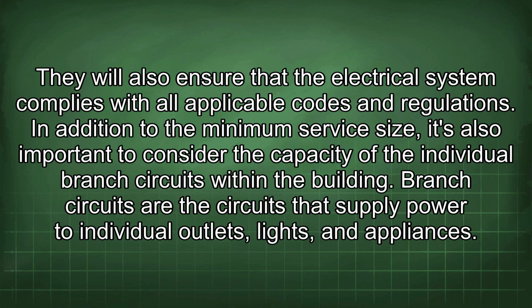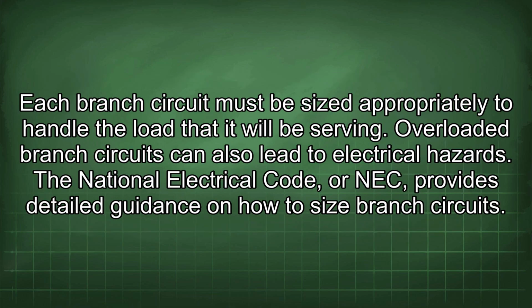In addition to the minimum service size, it's also important to consider the capacity of the individual branch circuits within the building. Branch circuits are the circuits that supply power to individual outlets, lights, and appliances. Each branch circuit must be sized appropriately to handle the load that it will be serving. Overloaded branch circuits can also lead to electrical hazards.